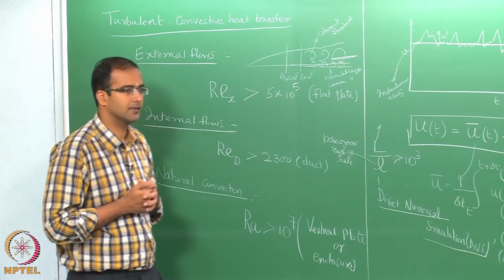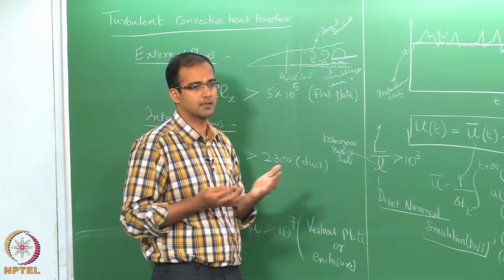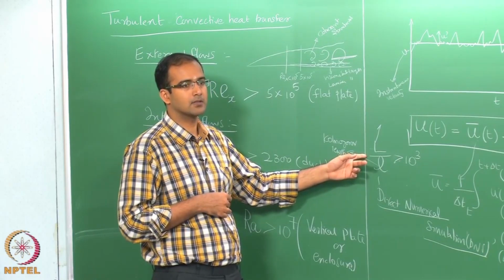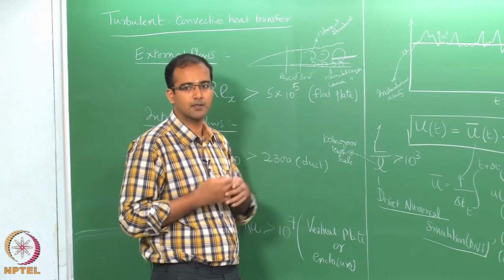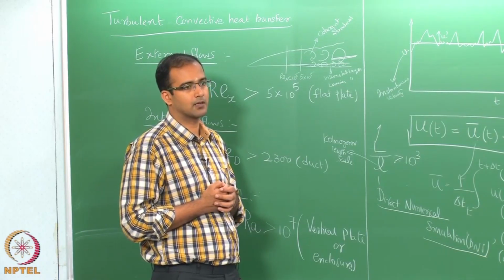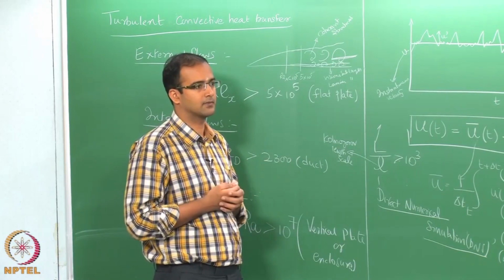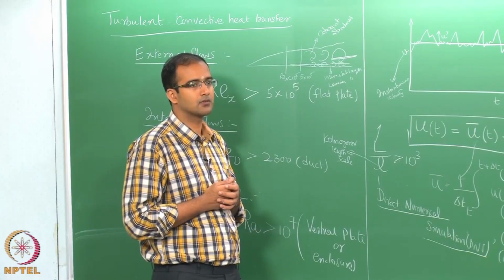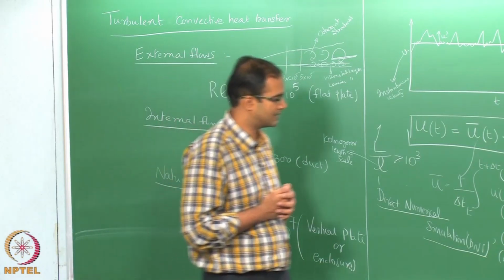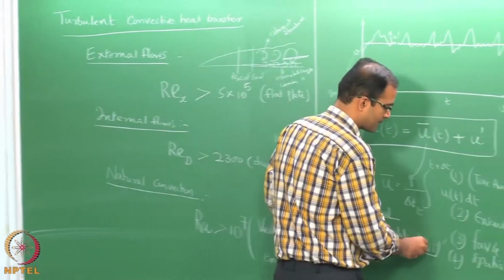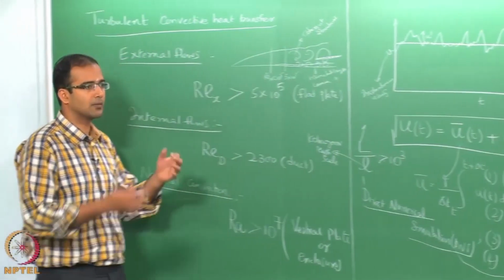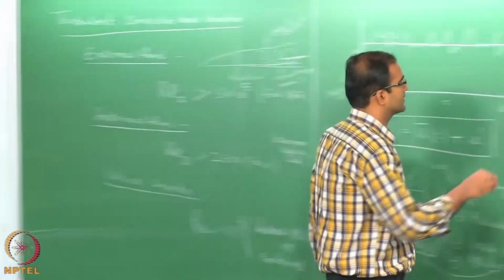So, this becomes a very challenging task, especially in 3 dimensions. This I am talking about in 1 dimension, but turbulence is inherently 3 dimensional. So, if you are doing a 3 dimensional simulation, then it will be a really humongous task. You are talking about a mesh size of 1 billion typically, just to do even basic turbulent simulations, which will be very computationally challenging. So, therefore, the alternate option is doing other approaches like large eddy simulation, or the more practical method which is called Reynolds averaging.